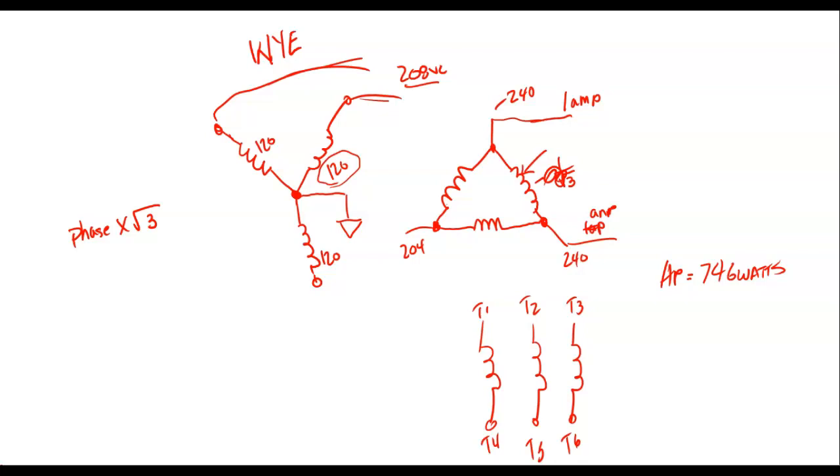The problem we have with these big motors, we talked about this the other day. So let's say I have a 200 horsepower motor, and I start that thing up. How many horsepower is it going to try to develop when we start it? The start current is 6 to 8 times. The voltage doesn't change. So that means a 200 horsepower motor could try to generate 1200 horsepower when you start it. 1200 horsepower can tear some stuff up.